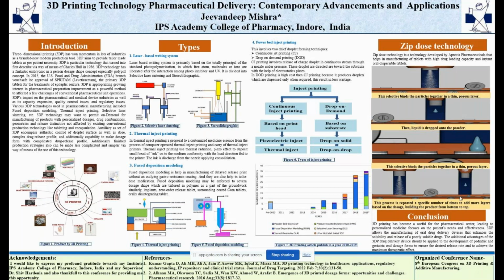They are divided into two techniques. First is continuous jet printing, the second is drop on demand printing. Continuous jet printing is a stream of ink droplets continuously ejected by a nozzle. The ink column is under pressure, and the charged droplets are affected and deposited using an electric field.